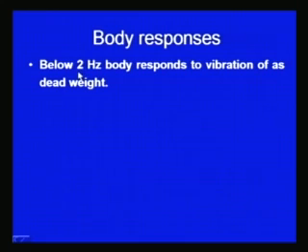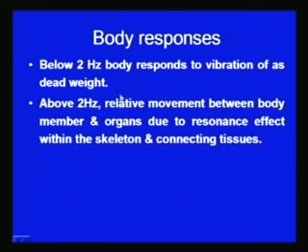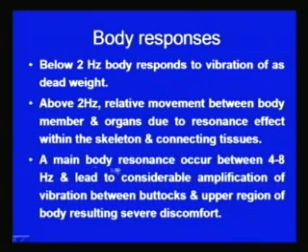So, for vibrations below 2 hertz, the body responds to them as a dead weight. But for vibrations which are more than 2 hertz, the relative movement between the body members and organs, due to the resonance effect with the skeleton and connecting tissues, is found to cause more discomfort to the operator.